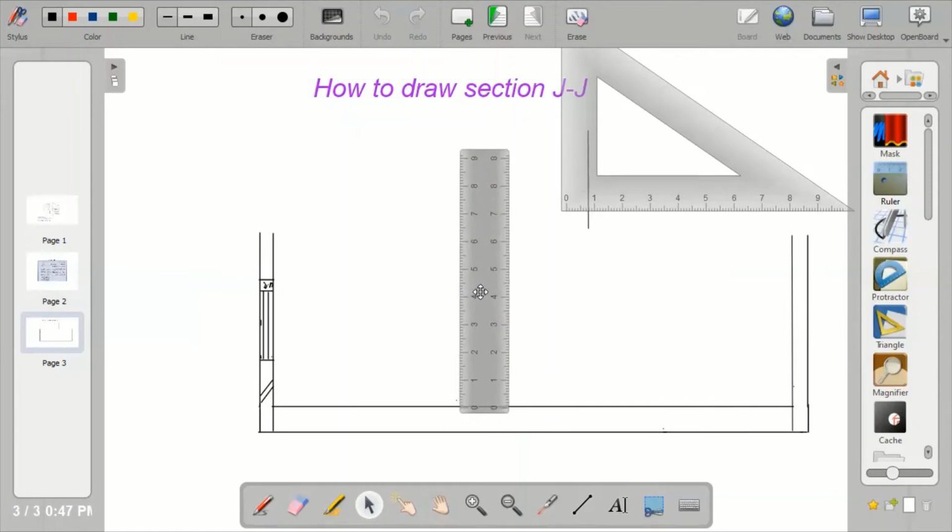I will also use the same height of the building. The height of the building is 3.2, so I'll just bring out 6.2. No, the given height is 3.1, so I'm going to bring out, like we did for the first one, 6.2, which is 3.1 times 2. Then I'll also draw the thickness of the wall. Okay, at this point, I don't need to draw the thickness of the wall because when I'm looking at the arc, I will only see a straight line.